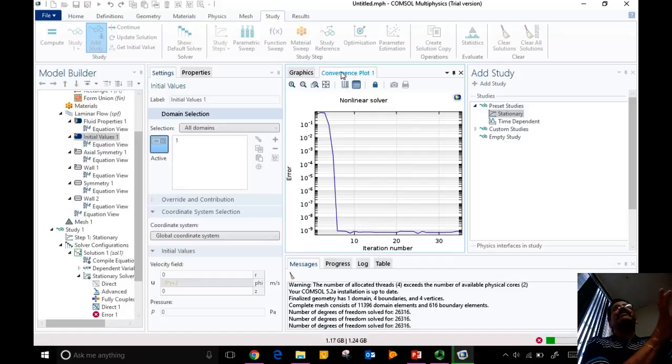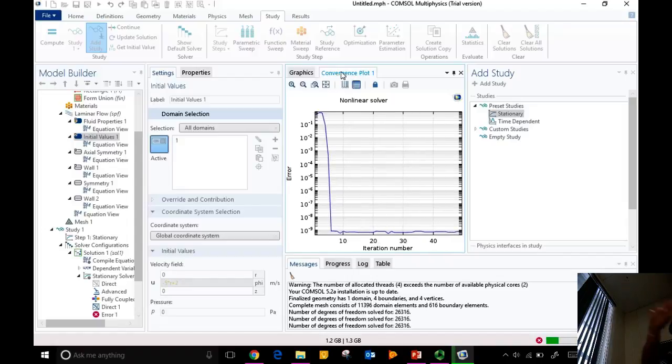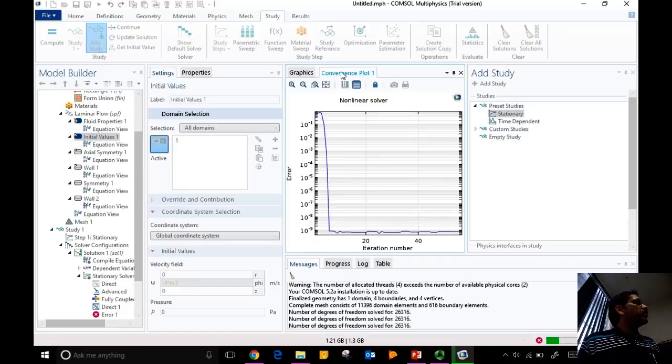It's solving the full Navier-Stokes equation. Sometimes it comes from the fact that the problem is unstable, physically unstable, like when you increase the rotational speed beyond the critical Taylor number, you will find these cells. And that's going to take a lot of iteration to jump through that transition phase. And so you don't know what is causing this instability in this convergence problem, whether it is numerical issues due to nonlinearity or whether it is physical instability. No artificial intelligence has come in yet to address that, but one day it will, I think.